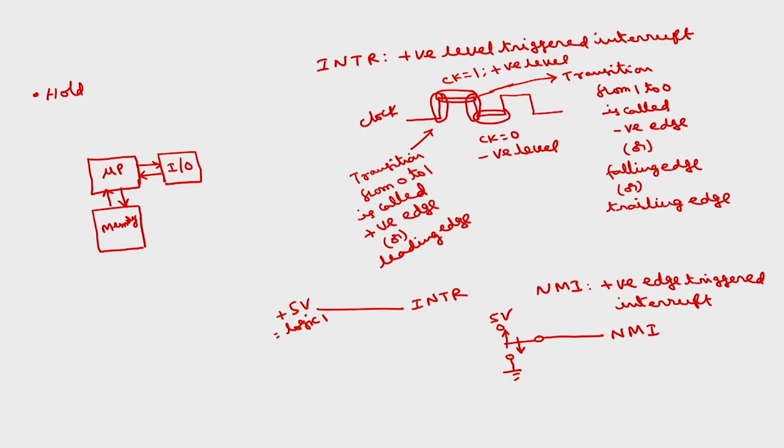As I have told, the microprocessor is useless unless it is connected to memory and IO. Because the microprocessor has address and data buses, if the memory wants to transfer data to the IO, the regular process is that first memory transfers the data to the microprocessor, then from the microprocessor the data goes to IO.